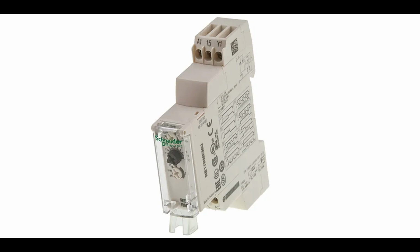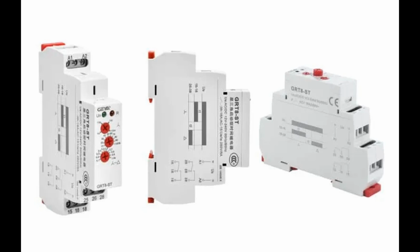Inductive load rating. Inductive loads, such as motors and solenoids, can generate back EMF, electromotive force, when de-energized, which can cause arcing across relay contacts. Time delay relays intended for use with inductive loads should be rated accordingly to withstand the associated arcing and prevent premature contact wear or failure.